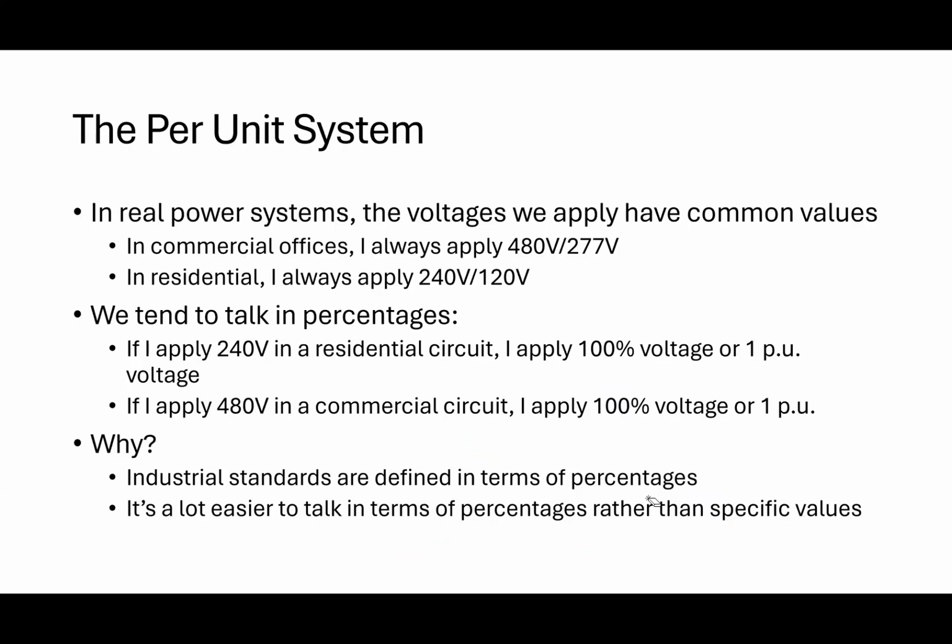So that's kind of all I need to know, but I want to talk about some practical issues. Most of the time, these are all single phase transformers. You look at most transformers that are out there in the world, they're usually 3-phase transformers. And 3-phase transformers are a bit more complicated because you can have a delta connection on one side and a delta connection on the other side. You can have a Y connection and a Y connection, or a delta and a Y, or a Y and a delta. So there's a lot of ways to do that. I'm not going to talk about that stuff. It's a little more complicated, right?